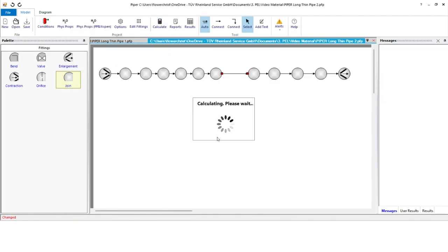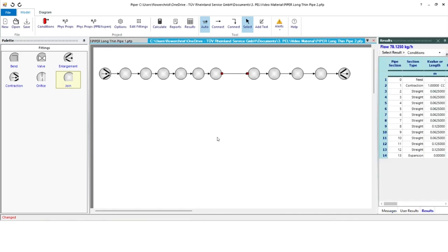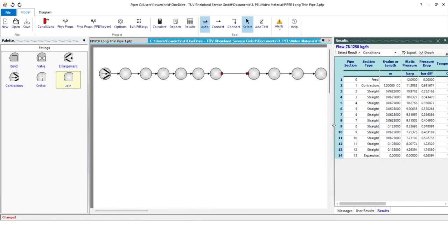And then we're going to press calculate. The solver's going to go and have a think. And then we've got a result. Because we've managed to split this pipe up into little sections, it's just helped the solver go through that pipe work, keep iterating through. It's not hitting inconsistencies. It solves relatively quickly, relatively stably, much more stable than the other one because that gave us errors, and this gives us an answer.